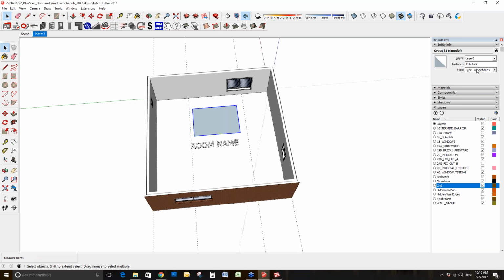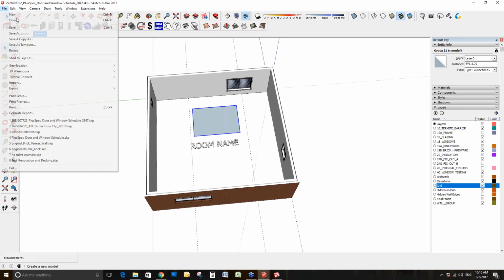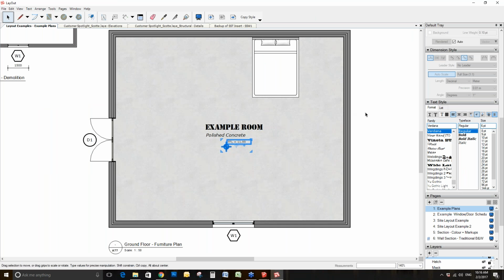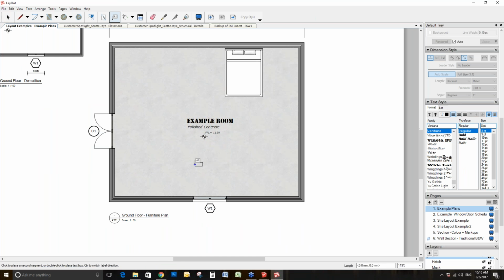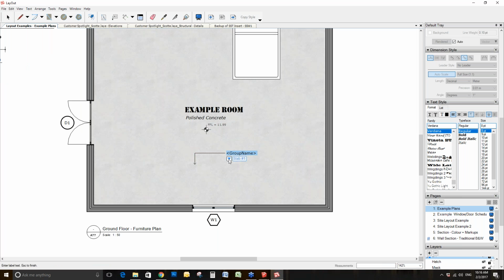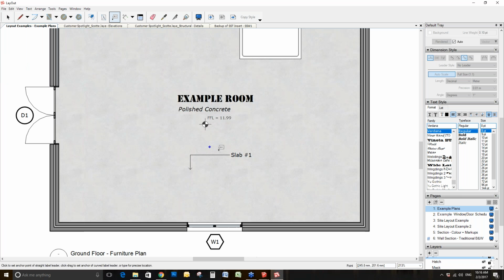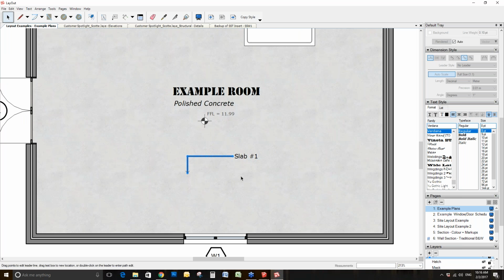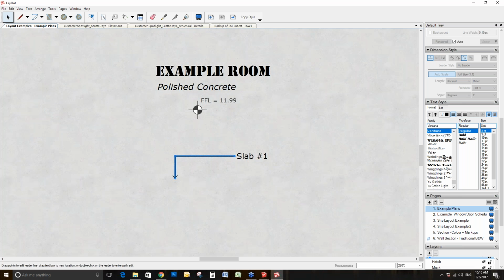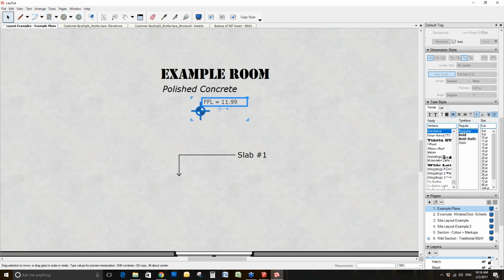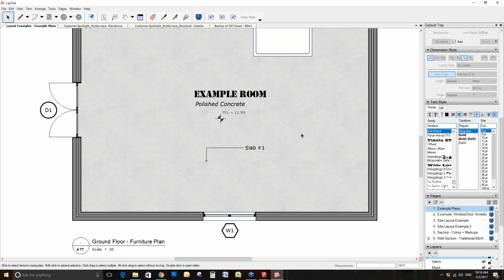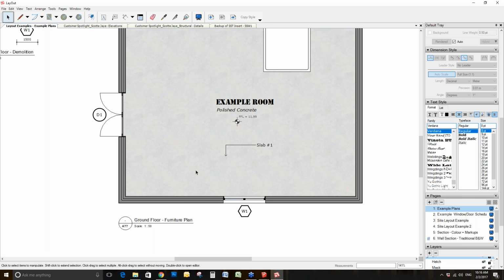Right, once you've done that, you've now got the finished floor level 3.72. You can save it, you go back into your layout file, and if you use your annotation, you can grab a point, and then you can click on this down part, and you'll be able to pick out your FFL, whatever it is, and therefore it's smart annotated. Now, then you can simply hide this part or delete it if you don't need it, and then attach it to the symbol. So you'll be putting your symbol there and having it work the way that you want it to work. You can then create a scrapbook of it as well, so you can just continuously reuse that at any time.